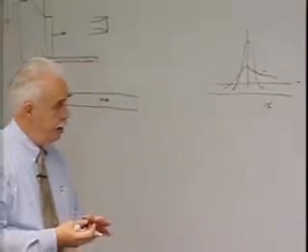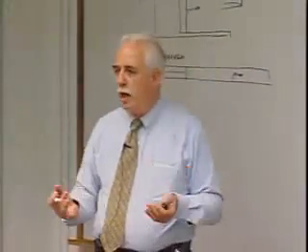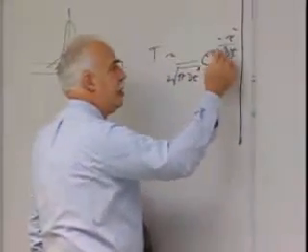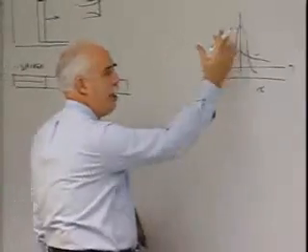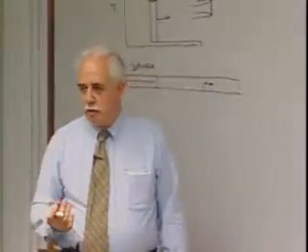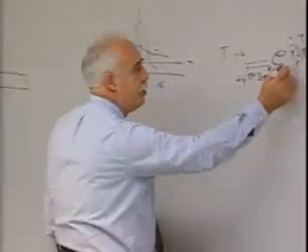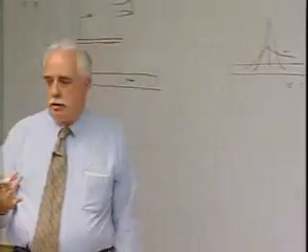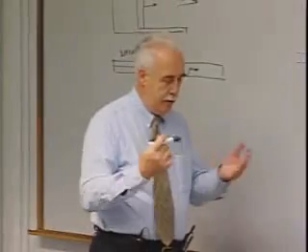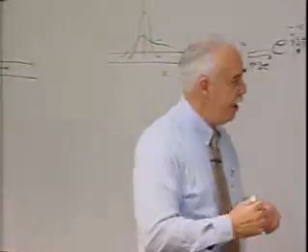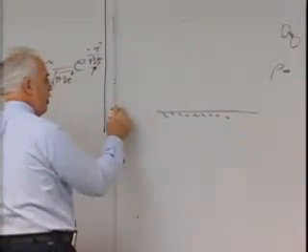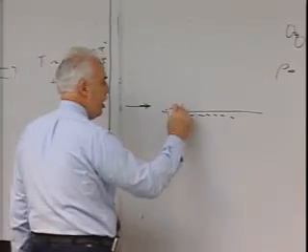Significant thing is when we talk about ablators, when we talk about tiles or thermal protection systems, this is the significant parameter. We have an extremely high temperature at the surface. The job is to keep the energy from the structure. Thermal diffusivity is the prime parameter. It is also not thermal diffusivity, but if you now consider simplest fluid mechanics, flat plate, first thing you learn about in terms of viscous flow. You've got some velocity coming along here, you've got a boundary layer that builds up.